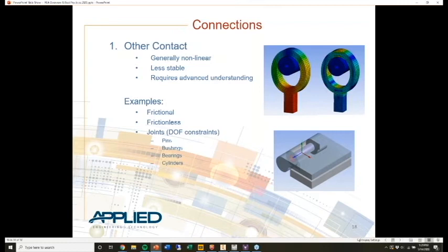We would actually use a frictional contact. If we were to use bonded contact there, our Hertzian contact stress in that situation wouldn't be anywhere close to correct. But if we want to calculate the contact stress using a frictional contact, we can get very, very close to the analytical answer there. And so that's a great example of the difference between those types of contacts.